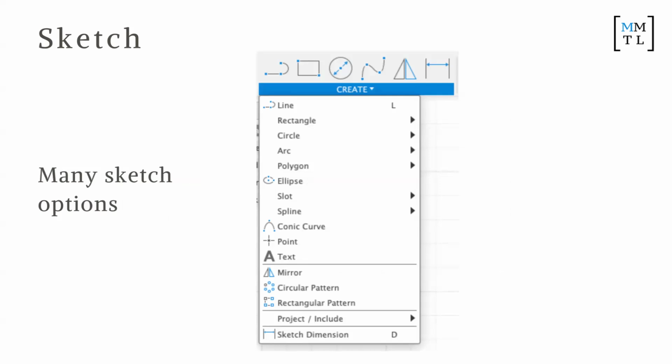So if you guys wanna just hover over each of the sketch tools, and then you can see. You just click sketch and then you click on the XY view, right there, top along the buttons. So basically what you did just now is you clicked the plane first and then sketch, but it's the same thing. You can choose the plane and then sketch, or choose the sketch button and then choose the plane.